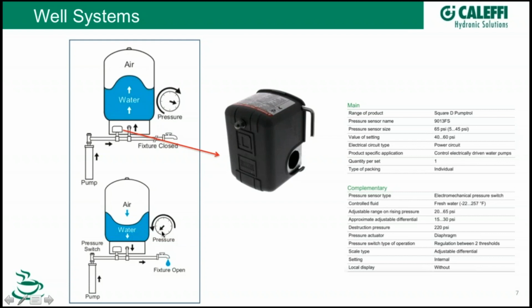When the pressure comes in, the gauge will change, and when you take water out, the pressure is going to drop to a predetermined pressure where the pump will kick on again. Most of the time those are going to operate around a 20-pound differential, and it could be a pressure switch, this switch right here, that operates at 30 pounds kick on, 50 pounds kick off. You can adjust those. You can buy different ratings. I think the one I've got on my house is a 40 pound cut in, 60 pound cut out.